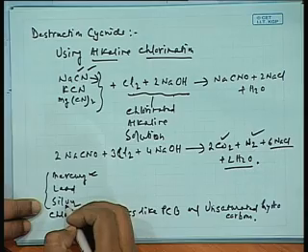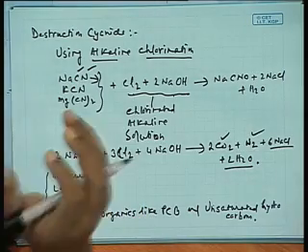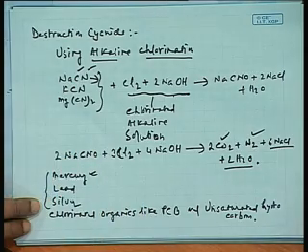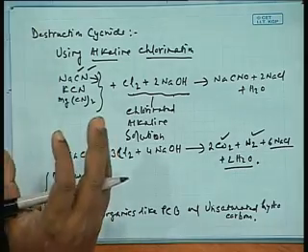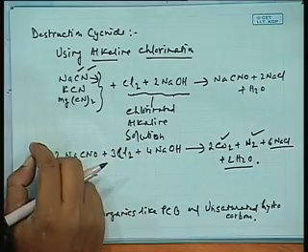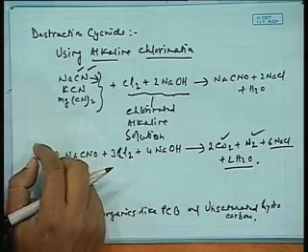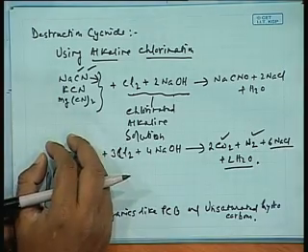So, when there are very specific pollutants to be eliminated from the wastewater, we would go for tertiary treatment. One of the very famous methods of tertiary treatment is redox reactions. There are many more, but this just gives you the basics of where and how these techniques can be used. Okay. So, here we have mostly discussed the treatment of wastewater.